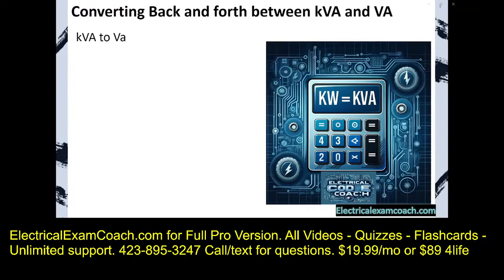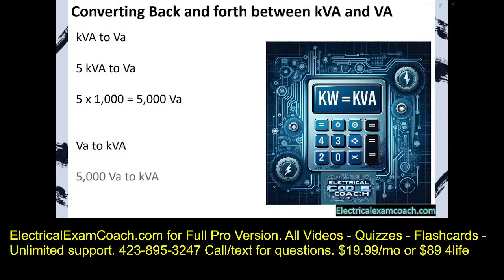Let's practice converting back and forth very quickly. Let's go from kVA to VA. So if we had 5 kVA and we wanted to go to VA, all we would have to do is multiply by 1,000, and that would equal 5,000 VAs. And the same if we wanted to go from VA to kVA, all we have to do is divide by 1,000, and it'll convert it over to kVA. You'll get very familiar with this and won't have to do any multiplying or dividing, but if you ever forget, that's all that you have to do.